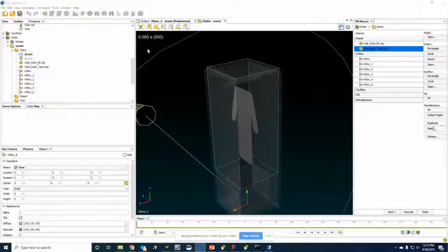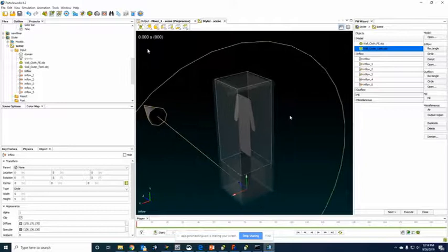I am going to go into each one and edit those so that they're in the right location. For each of these, I'll need to change the width and height to be 0.1. You can see that before that was a 5-meter circle, and now it's a 0.1 meter circle.